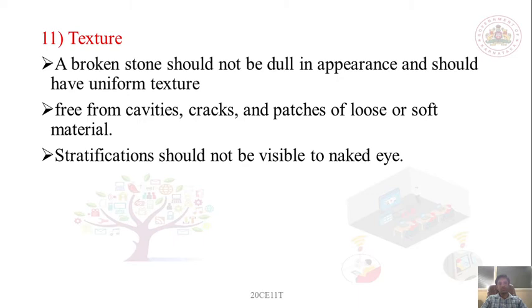The stone should be free from cavities. It should not have any cavities like holes. It should not have cracks on the surface of the stone, and the stone should not have patches of loose or soft materials. That is how the texture should be arranged. Stratification should not be visible to the naked eye.